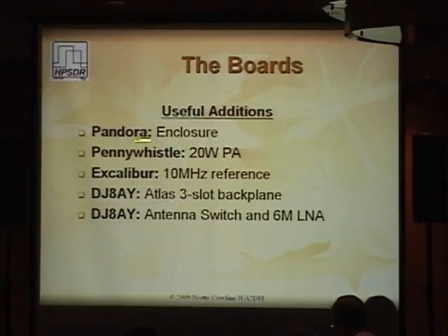Excalibur is a 10 megahertz reference. For those of you who a regular 10 megahertz oscillator isn't stable enough, you can use Excalibur to either feed in an external reference, like from a GPS, for instance, a very stable reference, or it has an onboard TCXO that you can use. Pretty versatile board. It's a little half-high board. That is in process of being kitted right now.